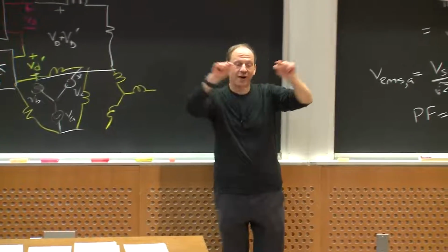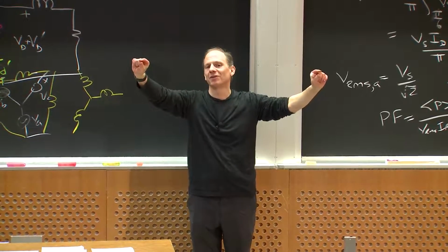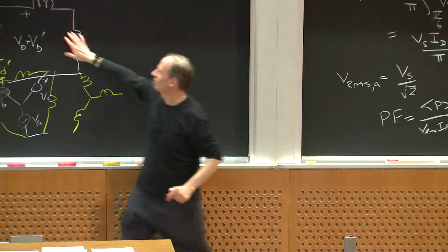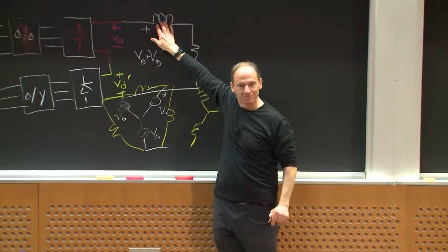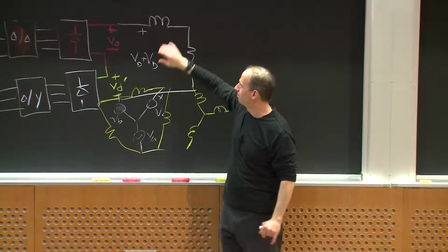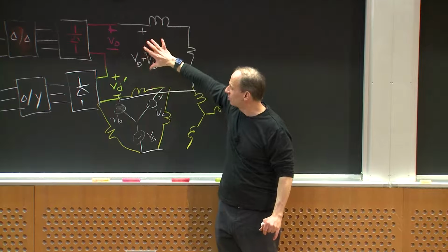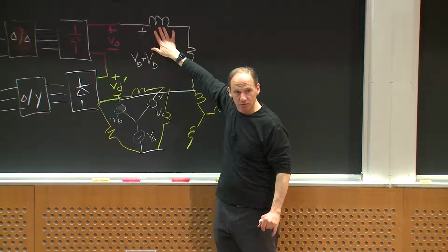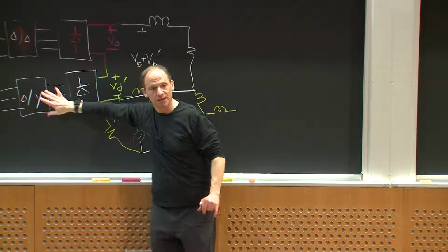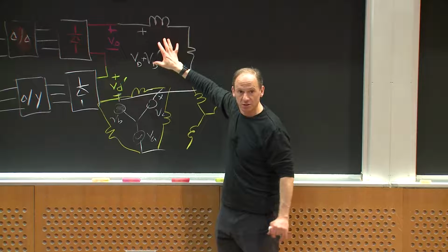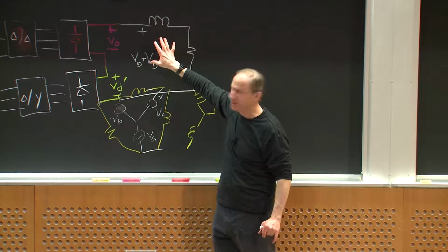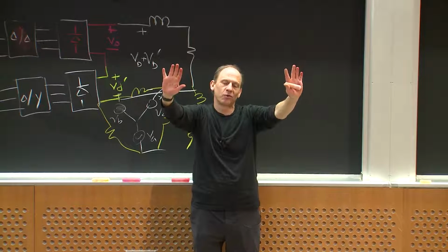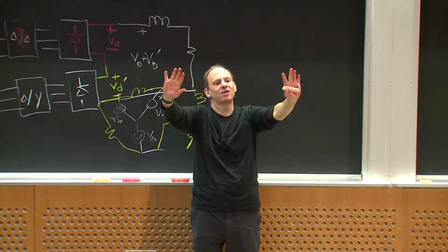And so first of all, I have higher frequency again, 720 hertz is the fundamental ripple, and by the way, the amplitude of that ripple is again smaller, so this inductor again gets smaller. The net result is that we get really small filtering. I'm trading numbers of devices and complexity for really good output ripple at higher powers, in this case, higher voltages. I can play the same game with what's known as an interphase transformer and get much higher currents if I prefer instead of higher voltages.